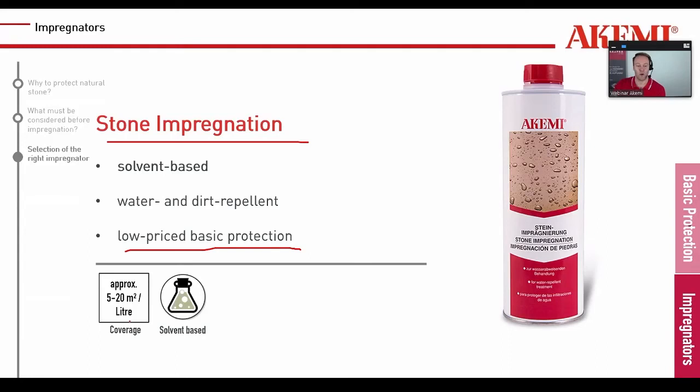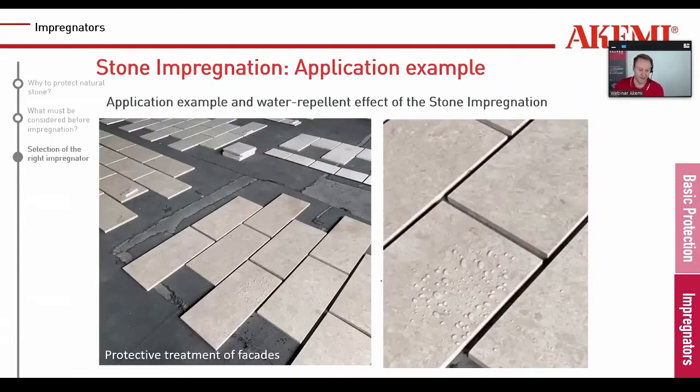You can see here, there's a dry lay of some facade tiles, and they treat it directly in the workshop. So this is ideal. You're not relying on any weather conditions outside, not on whether the sun is warm or if it's raining or if it's too cold. When you can do it in the workshop, it's even better. You dry lay your stones, you treat them directly, and then you bring them to your site. You can see here they do a water test, and you can see how the water is beading, so nothing is penetrating inside.